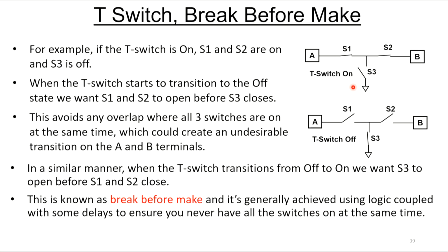operation. And for example, if the T switch is on, S1 and S2 are on and S3 is off. So that's this configuration here. And if we're saying we're going to transition from the on state to the off state, so S1 and S2 are going to be opening and S3 is going to be closing. What you don't want to do is you don't want to have all three of these switches closed at the same time, because that's going to pull your inputs A and B to ground.